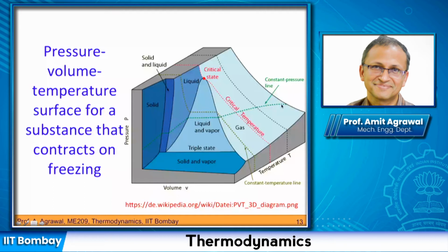Now we have talked about the terminology. We are talking about superheated vapor is what we're starting off with. So we're starting off with some point here. Follow the cursor. As you follow the cursor, you are still in the superheated region right now. But at some point you will hit this boundary, which is the liquid vapor boundary. And then, if you continue with the cooling process, your vapor will start condensing.